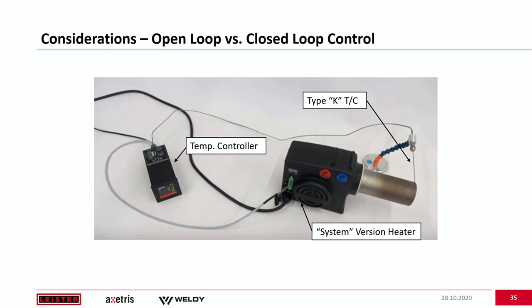Now it wants to send this information back into an external controller. It could be a single temperature controller, or it could be a PLC. Now, the external controller itself is really the workhorse of the process. So what it's going to want to do is take that information that's been provided by your TC, look at it, and then make the appropriate control signal adjustments out to the heater so that the heater responds accordingly and you get the temperature necessary for your process.